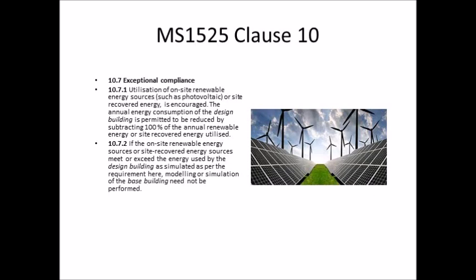What it says there is utilization of on-site renewable energy sources such as photovoltaic or site recovered energy is encouraged. The annual energy consumption of the design building is permitted to be reduced by subtracting 100% of the annual renewable energy or site recovered energy utilized.